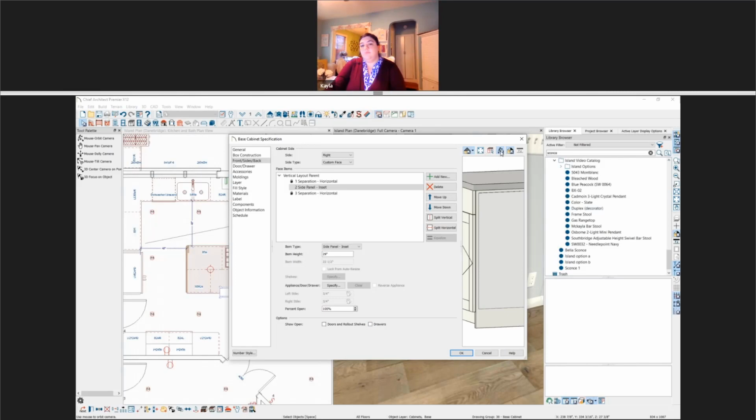So one of the things you could do as a potential is you could place the panel that you want separately. So don't put it on the cabinet. Place it separately in the plan, position it in your elevation view, and then you'll be able to see it.